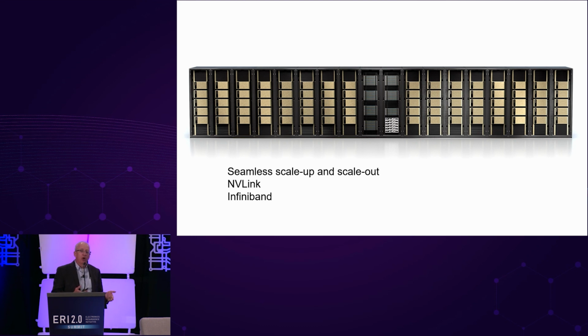And by scale up, we have a technology we call NVLink and NVSwitch that allows you to build today with Hopper up to 256 GPUs that can do load store instructions to each other's memories over NVLink with essentially no overhead. And it looks like one big GPU, but with 256 times the performance. Of course, there is a bandwidth taper compared to the 3 terabytes per second out of your own HBM memory.